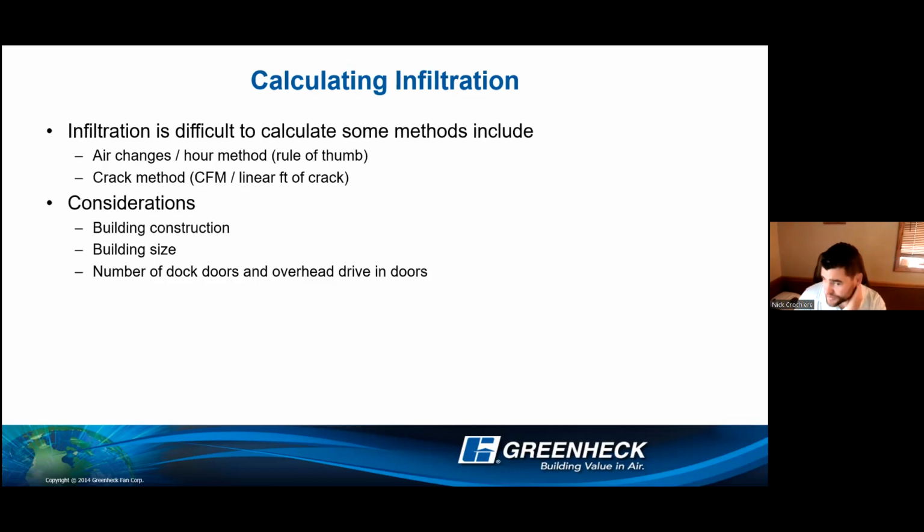when you're looking at that building construction is insulation. That's the key detail. Just moving an R value of 1 digit or just a couple digits will drastically change your overall heating load for that building and the infiltration. So it is very, very key that the right details are gained in the exact building details, because I have seen selections go from 4 units to 8 units to 10 units, all depending on a very small variation of the actual insulation value of the roof and the walls. So it is very key that that is exact of what the building actually will have.